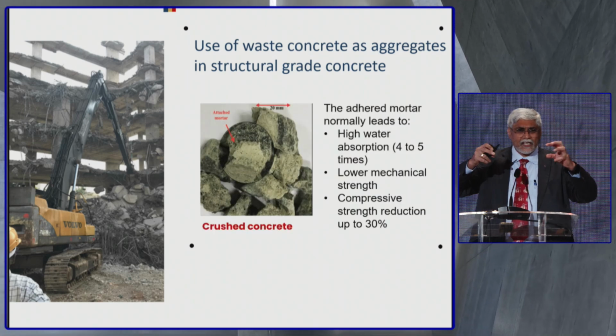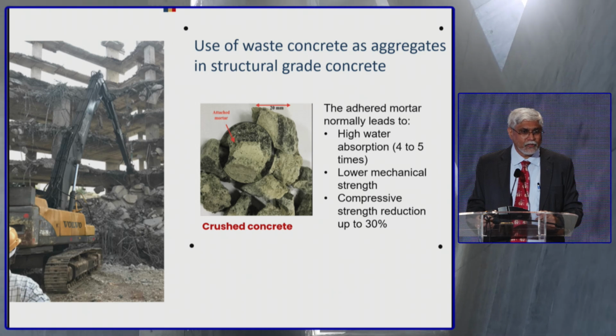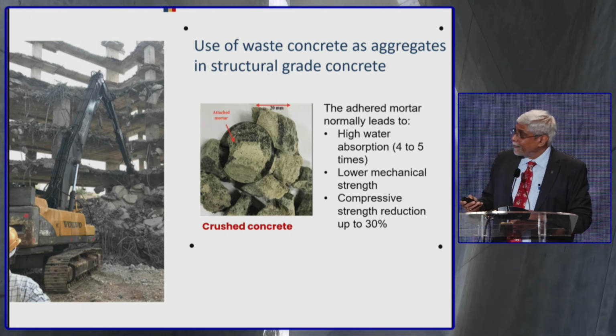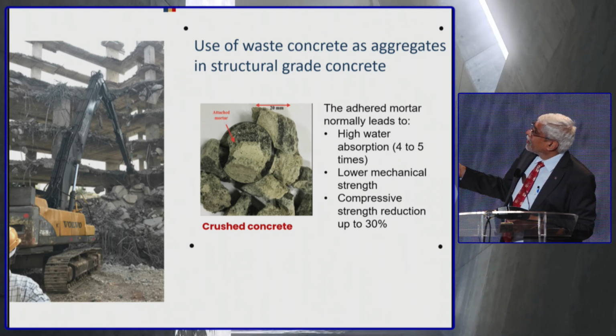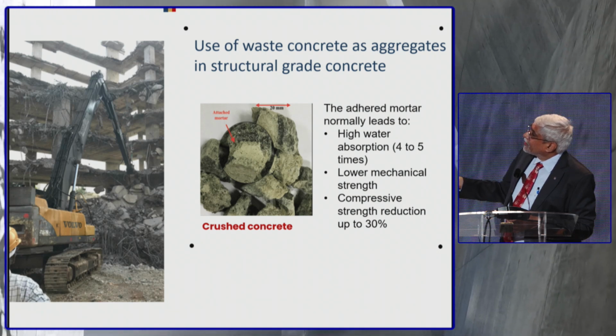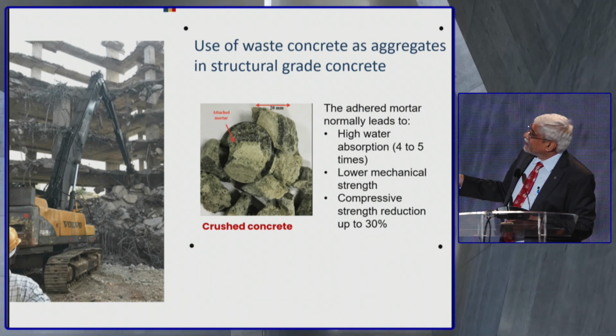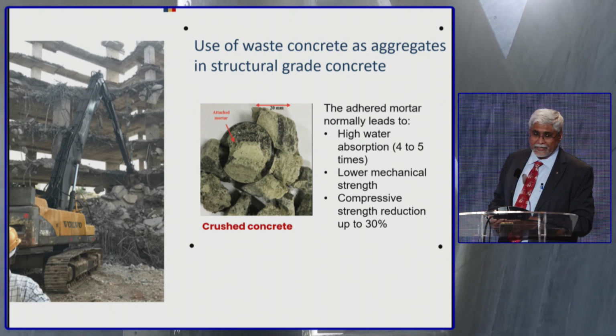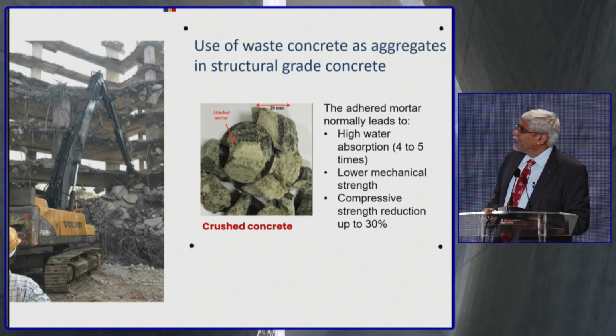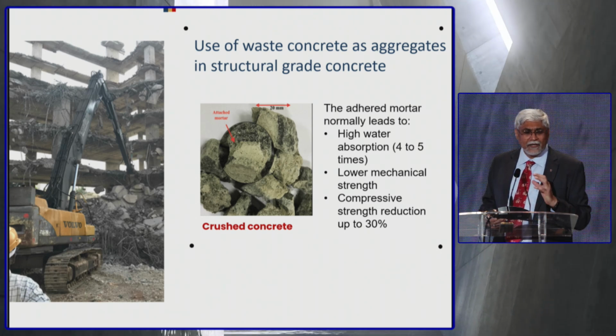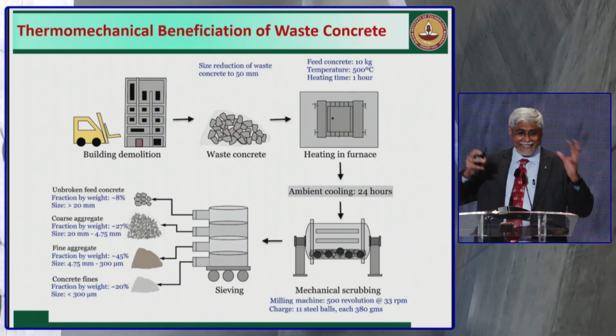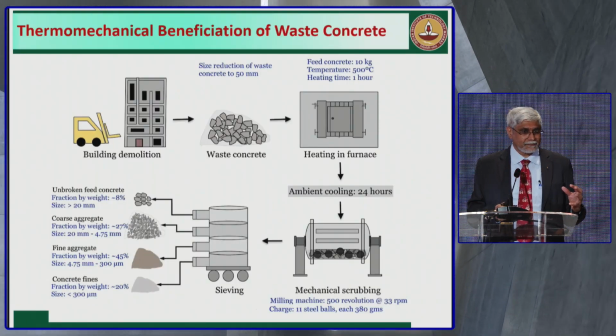We cannot just crush and put the concrete back into new concrete because it doesn't work. It has very high water absorption. There is a lot of mortar still stuck there. The strength will go down and the compressive strength will reduce. So I'll show you some results where we are trying the process of heating and then crushing.